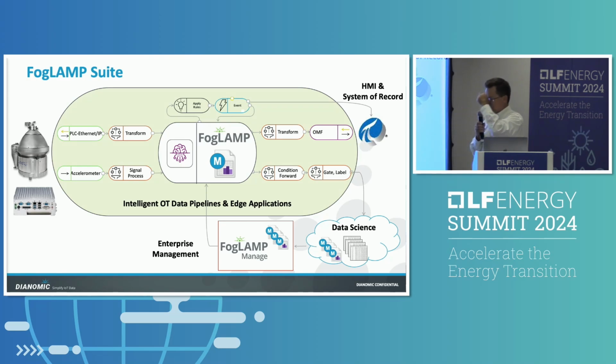And then we do something called gating. So it's interesting to get vibration data, but I want the vibration data to have the label of what the machine was doing at the time. So we take the 2 data pipelines right on the edge, and we see here's the RPM, here's the heat, here's how the valves were set coming in and coming out of the centrifuge, and we automatically begin labeling the accelerometer data, saying here's what the machine was doing when it was vibrating like that.